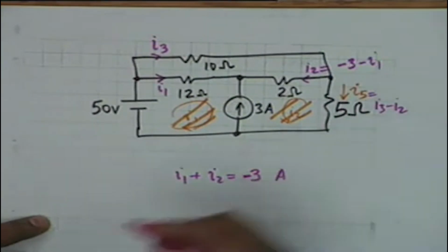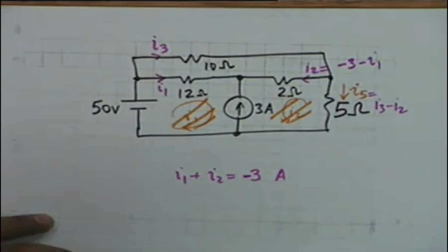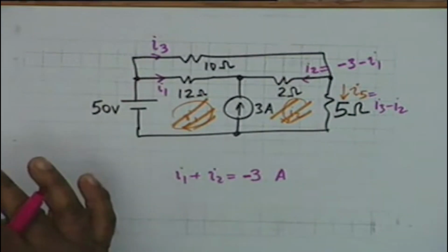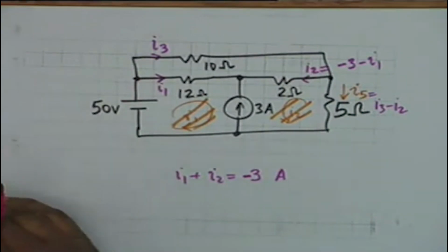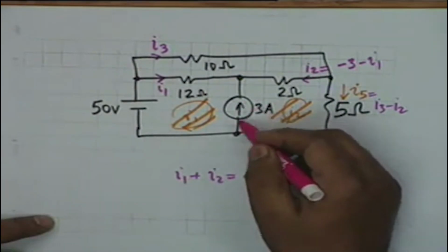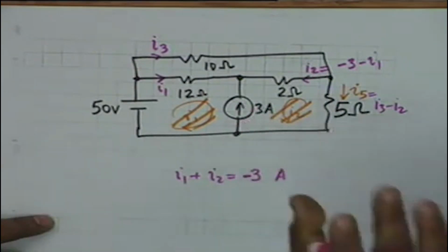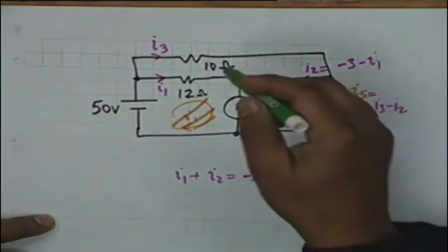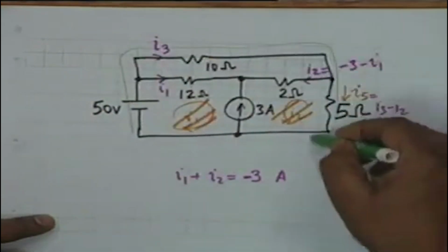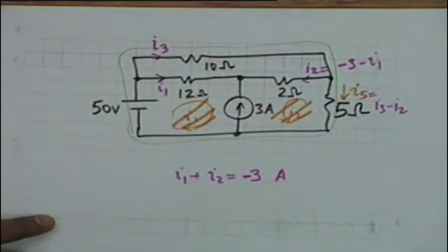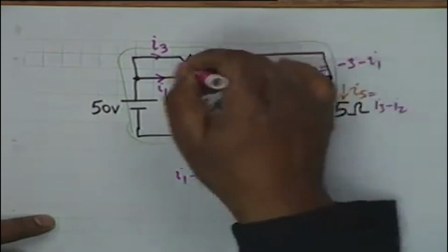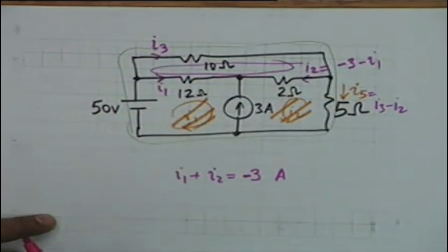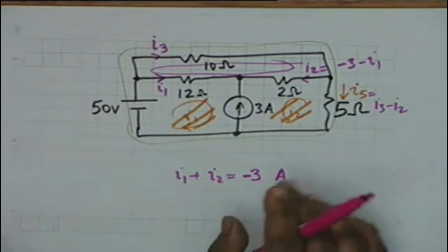And therefore how many currents are unknown? Only 2. And it suffices to write 2 loop equations. Now, carefully avoiding the current generator. The current generator must not be inside a loop. So what is the choice? The bigger loop. Well, you can go like this. This is one loop, and the other one is the upper loop. Okay, 2 loops which do not contain a current generator. That is enough, because there are only 2 unknown currents.